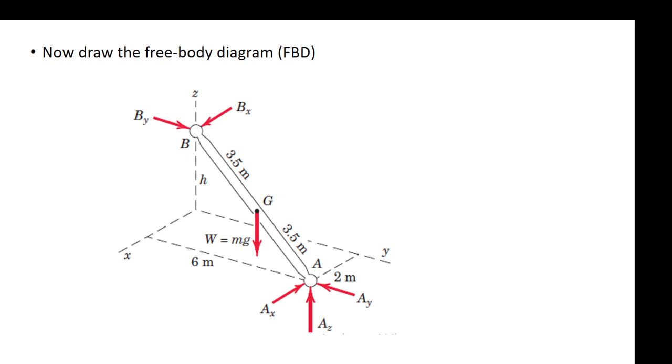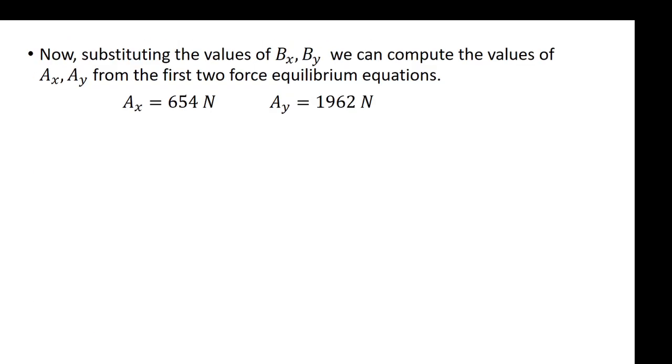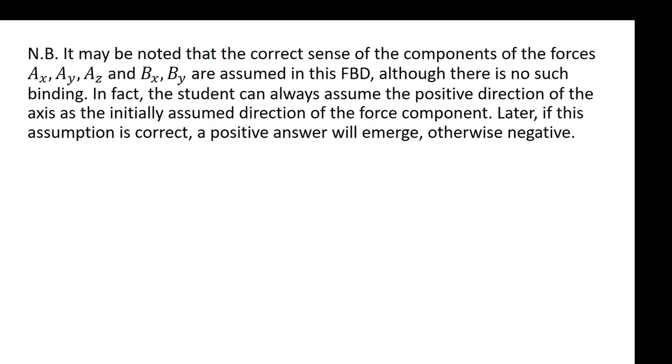Also, with respect to this diagram, I can comment lastly that I have sensed correctly the direction of the reactive forces. But how will you know that unless you solve it? In complicated problems, the force components might be in other directions. Don't worry about that. You arbitrarily select them. If you are correct, the values from the manipulation will be positive; if not, negative, telling you that you assumed the opposite direction, nothing else, and everything else will be fine.